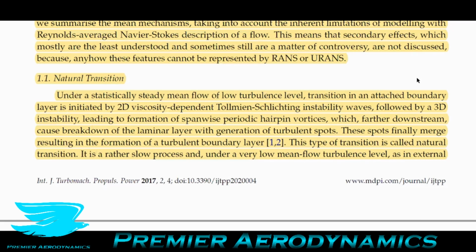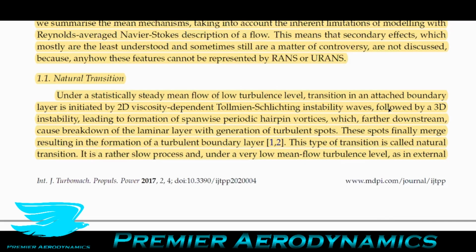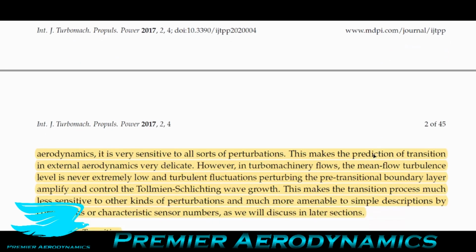I jumped ahead a little bit there. I talked about the turbulent spots and then the final transition. So these spots finally merge, resulting in the formation of a turbulent boundary layer. That's what I mentioned at the last bit here. But that's this general mechanism, and this type of transition is called natural transition. It is a rather slow process and occurs under a very low mean flow turbulence intensity level, as in external aerodynamics. And it is very sensitive to all sorts of perturbations.